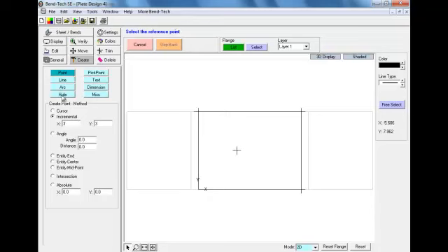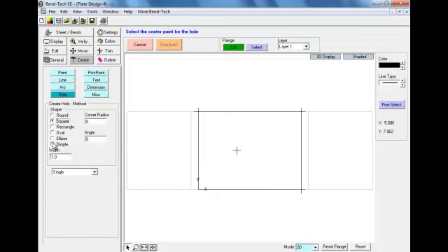Then we can go ahead and create a circle on that point. We're going to use a square hole in this case with a 2-inch width. Selecting our last point we created, we can now place that hole. We're also going to create a cutout in this flange.